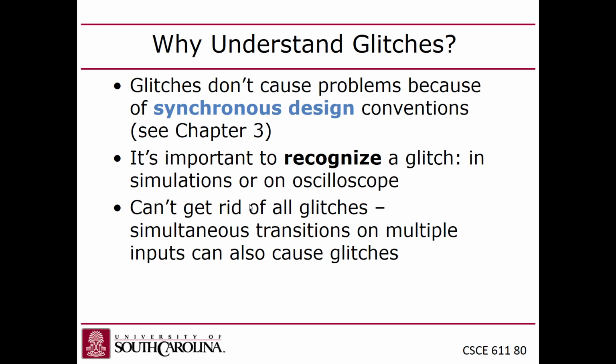So if the gates are pretty much like capacitors, then how do the capacitors discharge quicker than they charge, like go to 0 quicker than they go to 1? Would that cause glitches? Yeah, possibly, sure. The propagation delay will also be data dependent, depending on the rise time and the fall time, which could certainly be different. That's also the case because PMOSs are slower than NMOSs.